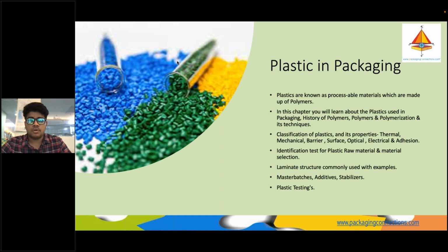And we will also discuss the identification tests for plastic raw material, and the material selection procedure as well. We'll also discuss the laminate structures commonly used in the current packaging industry, different laminate structures for different products and different commodities. We'll also discuss thoroughly what master batches, additives, and stabilizers are, why they are used in the plastics industry, and the testing of plastics as well.